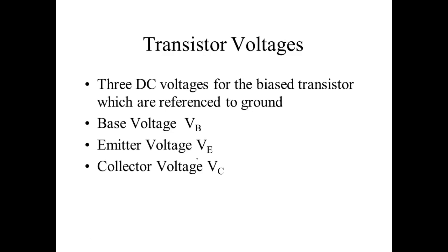Then we talked about the different voltages. This is very important, guys, because this is what you're going to have to solve for. You're going to have to solve for VB, VE, VC, VCE, and these different voltages. If you don't know what they mean, that's going to give you problems. And these are all relative to circuit common.